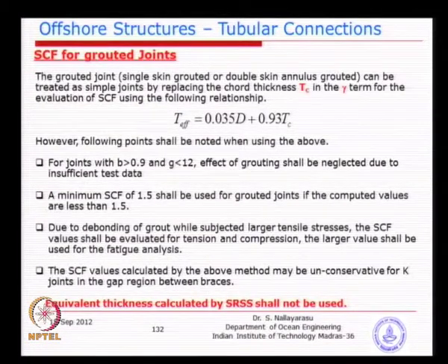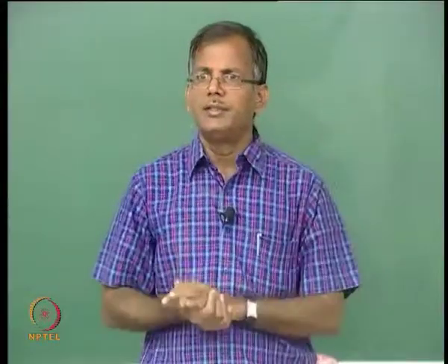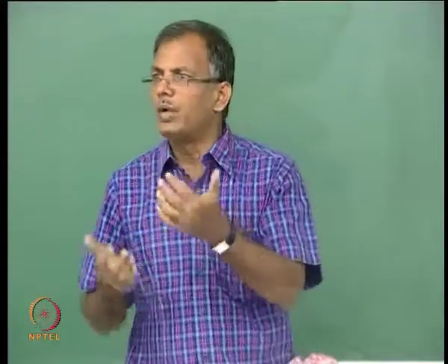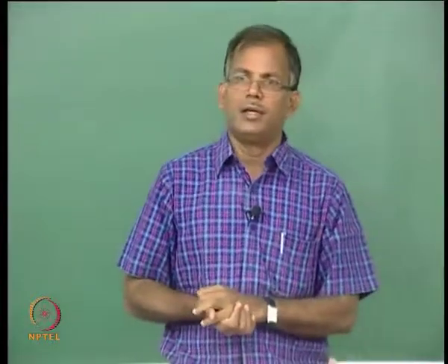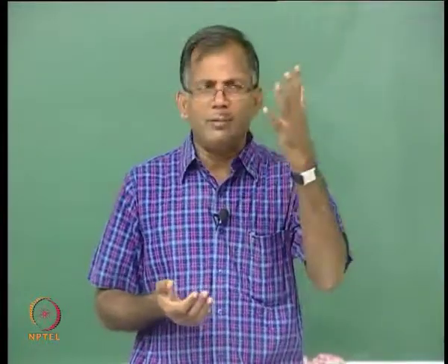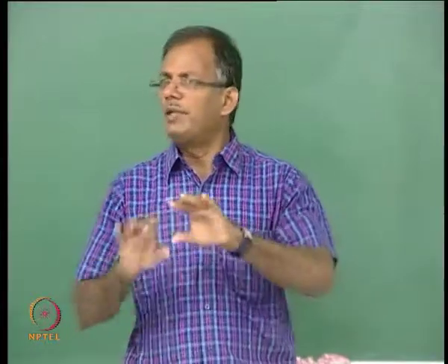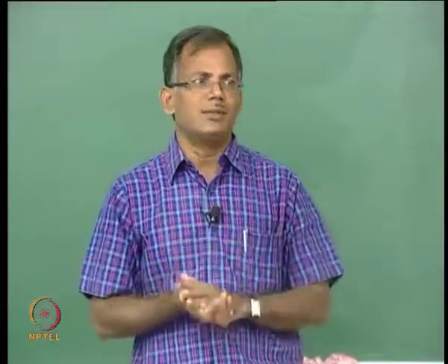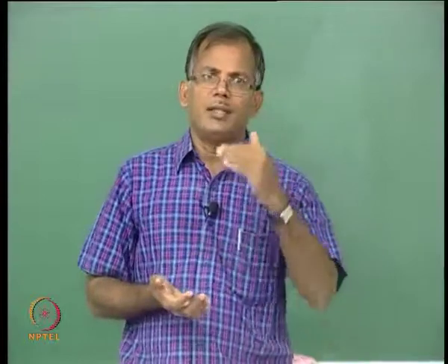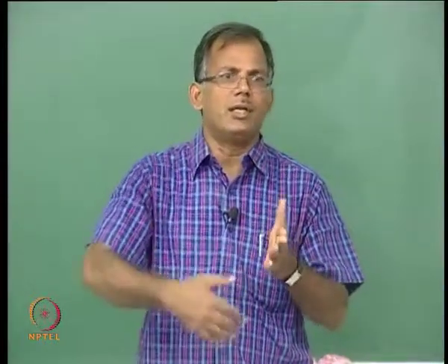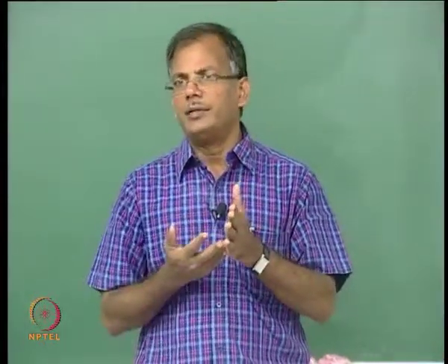The next one is the stress concentration factor for the grouted joints. Now just look back at what we did for the stiffened joints in static design. For example, for ring stiffened joints, we simply replaced the thickness with the equivalent thickness. That was one of the easiest methods. There were four or five methods I was talking about. One method is just replacing the equivalent thickness, and the other methods tried to do analysis using ring formulas and shear capacities.